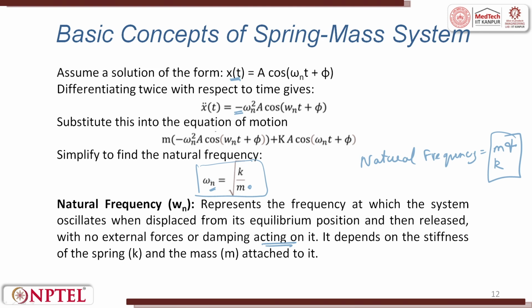Stiffness is a material property. You can play with stiffness. m is the mass. So, when we add mass, again there comes a design. You can change the design, the topology optimization. There are so many new techniques which have come into existence. So, natural frequency is very important to be calculated. The moment you know the natural frequency, we will plan our system accordingly. So, in natural frequency, without any external force, the system starts vibrating.